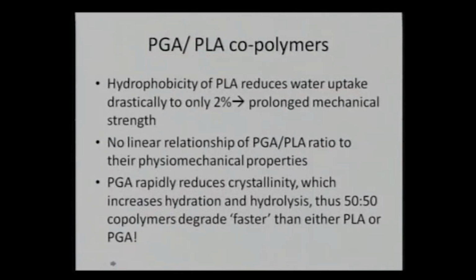And again, to appreciate the prolonged mechanical strength with the addition of PLA into the PGA matrix, we can see the hydrophobicity of PLA is so strong that it will reduce the water uptake of the thin film being developed from PGA-PLA by only 2%. So 98% of the water is basically not taken up, or is discarded. So with the addition of PLA, only 2% water uptake occurs for PGA for its hydrolysis.